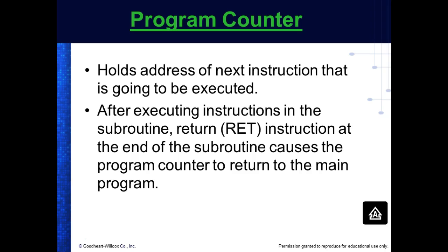You can go forward, you can go backwards. But how do you keep up with where you were? Well, you either stick your hand in there or you tag it, right? You understand that? Well, that's what the stack does. The stack is not the program counter. The program counter is what's actually counting through the program. So we're going 1, 2, 3, 4, 5, 6, 7, 8, and I'm fixing to leave this and go over here.